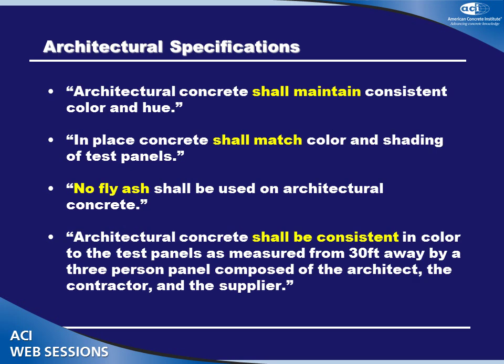Architectural specifications. Architectural concrete shall maintain consistent color and hue. That's one of my favorite ones, because my experience has been concrete changes color over time. In-place concrete shall match color and shading of test panels. No fly ash shall be used on architectural concrete. And this is my favorite one.